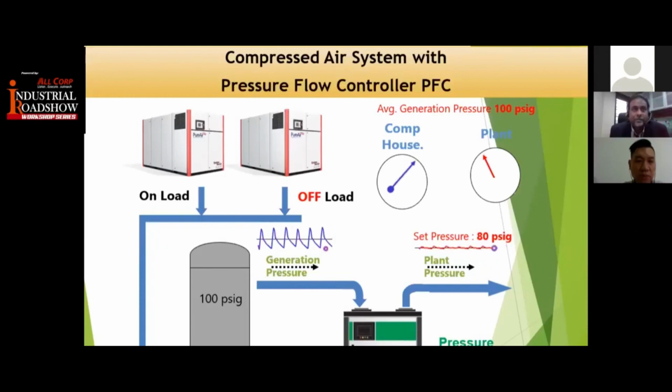In Singapore, it's very strict. LED lights must be below 10% harmonics level. So you can ask for a reference point: have you installed in any buildings in Singapore? If yes, then you know this is the right supplier you are selecting, right?